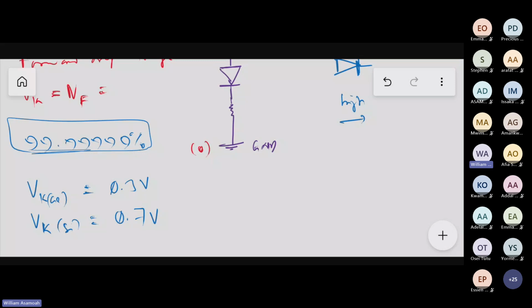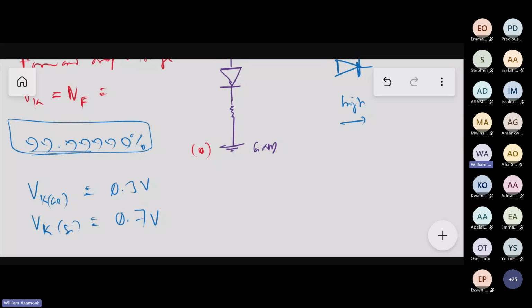And that became a very, very bad problem, because imagine you design your circuit hoping that it is going to have a knee voltage of 0.3, and because temperature changed, it has dropped. What that means is that your device can get damaged if there are excessive voltages around, right? Because its ratings start to fall when temperature rises. Its voltage ratings fall. So if you had rated it for 5 volts, then because temperature has risen, its voltage rating has fallen. That means that 5 volts now becomes too high for it.